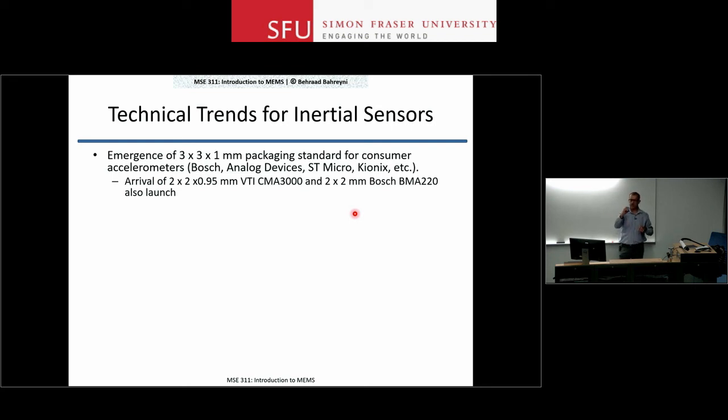So they get a die, the die that you saw in some of those packages. There's a MEMS die and there's an electronic die, and they give you that bonded piece of silicon. So they have MEMS and electronics as a piece of silicon. They hand it to you in order to make it easy for you to solder it onto your, let's say, PCBs and all that. They put some solder bumps on the top of the silicon, but that is it. There's really no package.